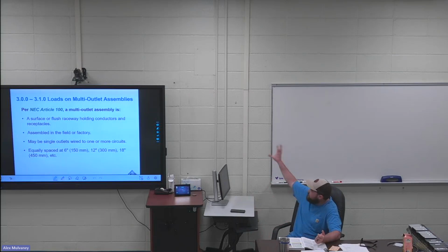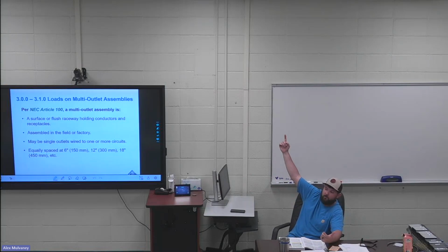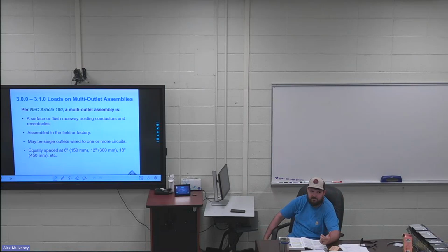So if this big wall was a show window, 18 inches of the wall is probably like one ceiling tile off. So within that ceiling tile, they have to have a plug, and then within 12 feet of that could be another plug. So say this whole wall was a show window. This wall is definitely not 24 feet long. I could put one plug right here in the middle within 18 inches of the window, and that would satisfy that code. Does that make sense?